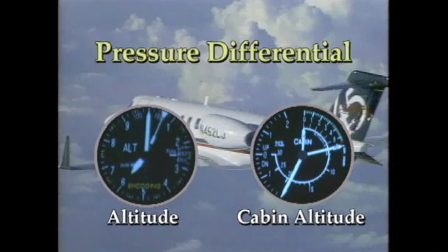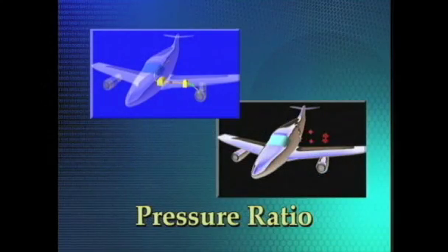Pressure differential. The greater the pressure differential, the more severe the decompression. Pressure ratio. When cabin pressurization is lost, aircraft compressors will continue to operate. The rate at which the compressed air comes in dictates how fast pressure is lost.